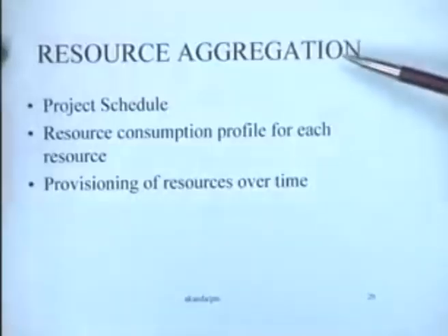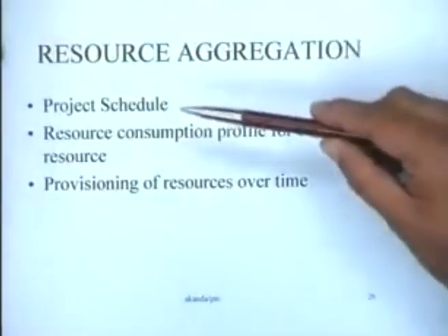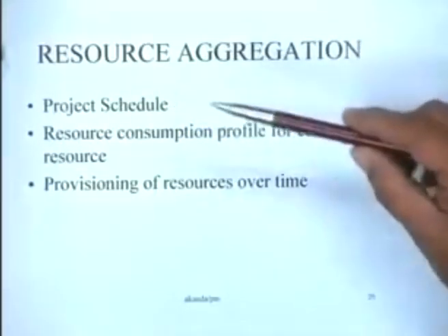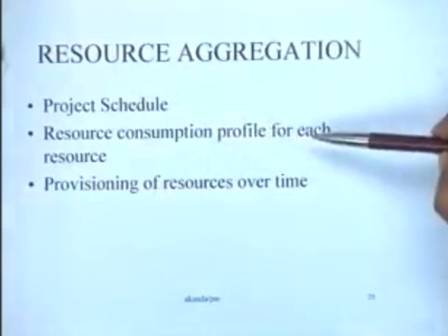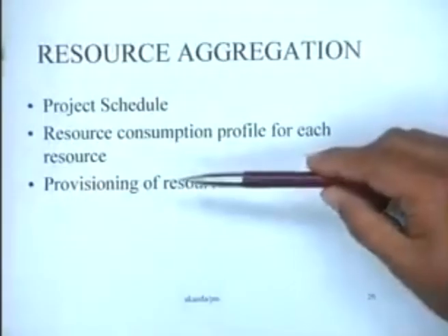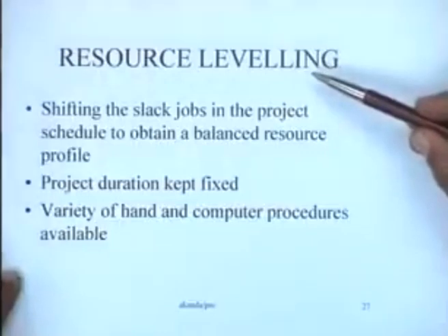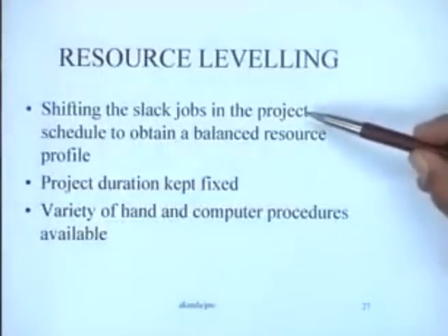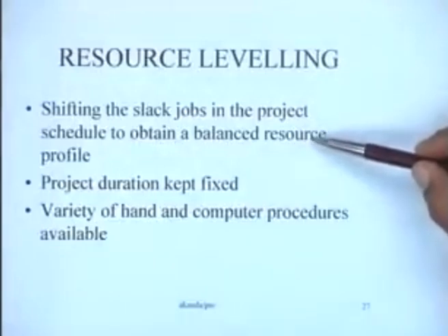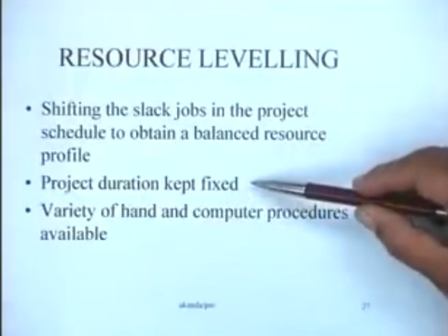Then I would like to just talk about some aspects of resources specifically. We can talk about resource aggregation, which talks about determining the project schedule, resource consumption profile for each resource, provisioning of resources over time, basically aggregating all the resources so that you know what is the total resource requirement, and then the process of leveling these resources by shifting the jobs which have slack to obtain a balanced resource profile, keeping the project duration fixed.